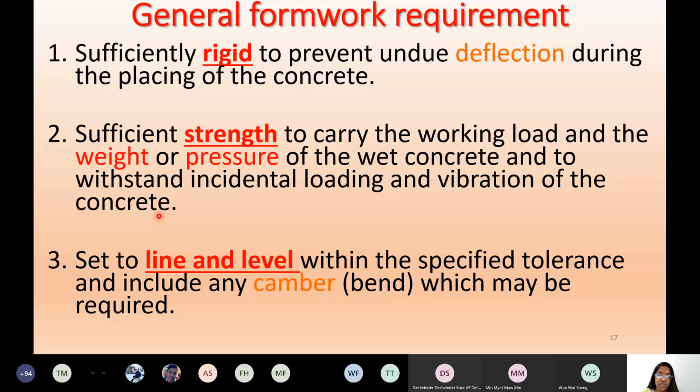So the vibrators should also not disturb the formwork. During vibration, if the shape of the formwork changes, like a square column, for example, changing slightly in a diagonal way, your size is lost, right? Your design is lost. The predefined designed load will not be achieved. The column will not withstand the load according to its design.